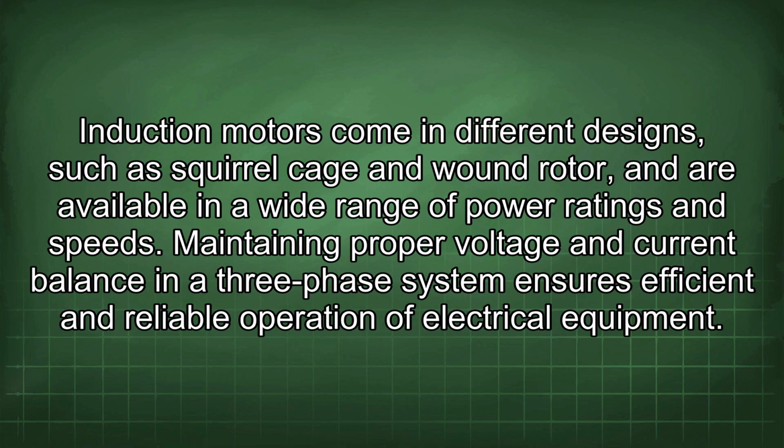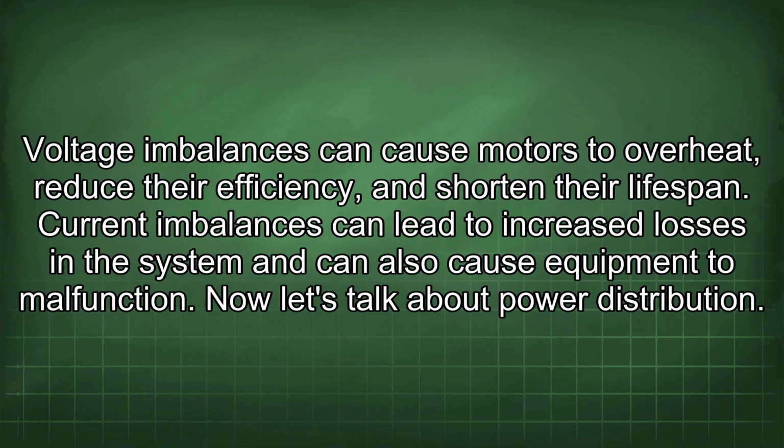Maintaining proper voltage and current balance in a three-phase system ensures efficient and reliable operation of electrical equipment. Voltage imbalances can cause motors to overheat, reduce their efficiency, and shorten their lifespan. Current imbalances can lead to increased losses in the system and can also cause equipment to malfunction.